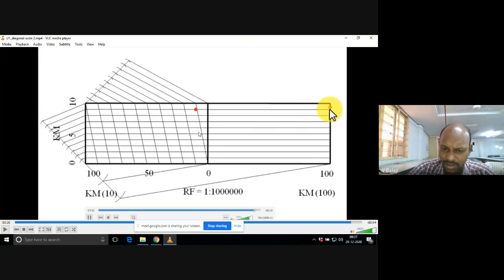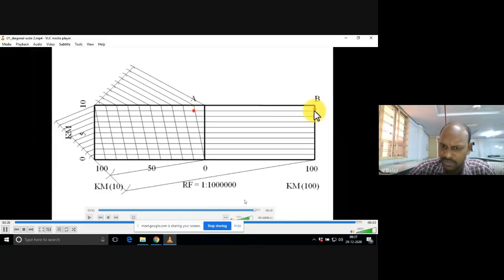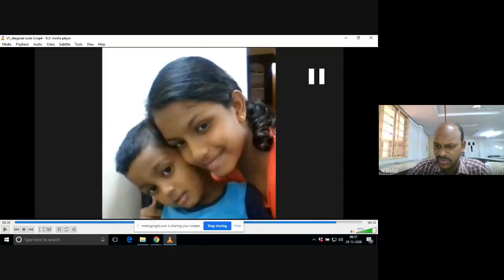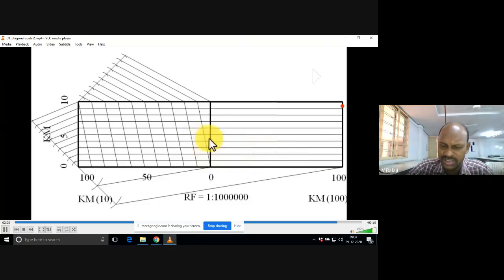Don't draw a slant line. Don't draw a line parallel to this one. Simply draw from this point. After getting the intersection of this inclined line and horizontal line, mark a point here and draw a vertical line with the mini drafter perpendicular to the baseline. And draw one more perpendicular here, which I call the extension line. Between these two lines, draw one horizontal line, which we call the dimension line. Mark on it the distance given in the problem. So what is the distance between those 2 points?